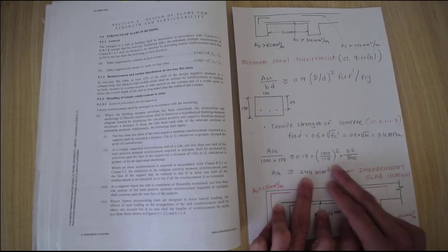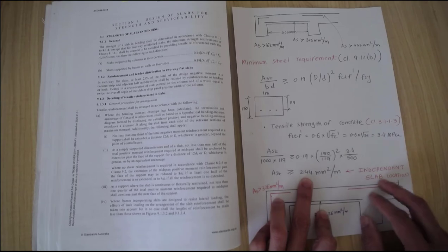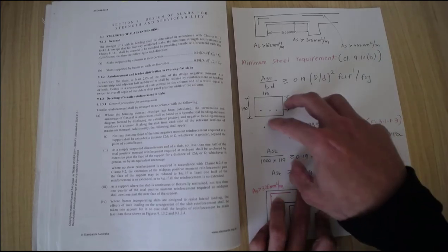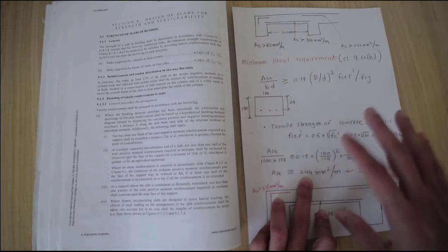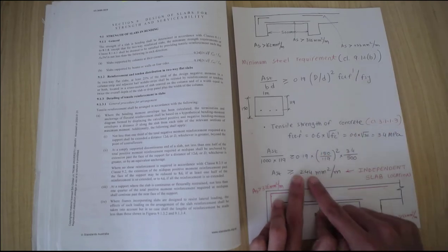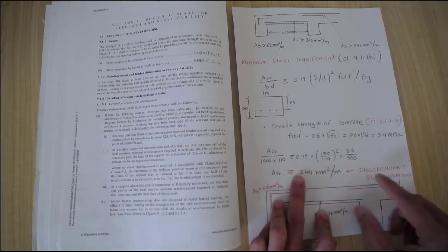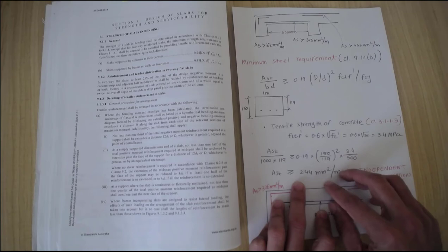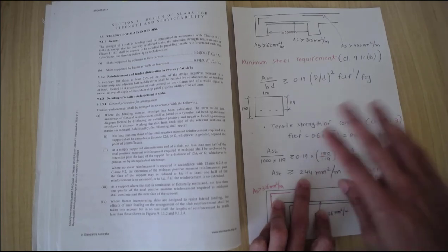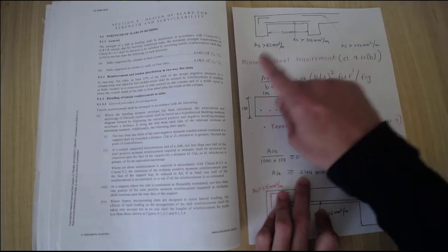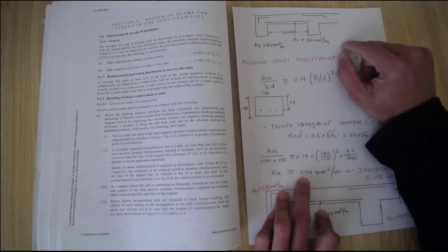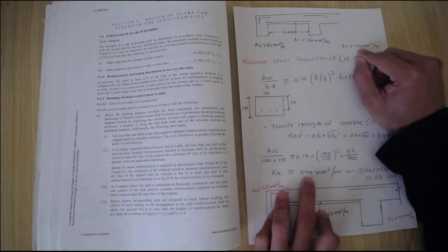Now for the whole slab, this is independent of where your slab is located. If you are designing at a corner, in the middle or on the side, anywhere, this Ast should be independent of where your slab is located. So we need to reuse this value and recheck the Ast value everywhere. Let's check it here. 433 millimeters squared.